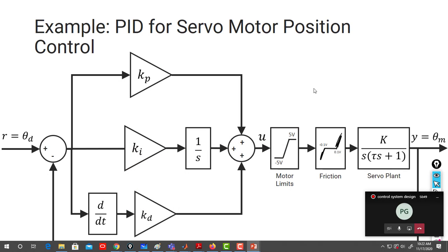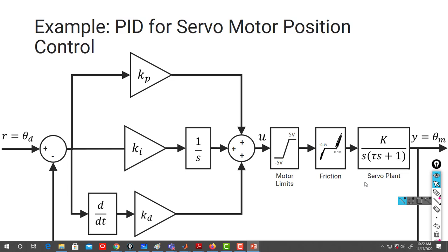Yeah, so you know, when you apply voltage to your DC motor, it doesn't directly turn on. It needs some minimum threshold voltage at which your motor will start rotating. And this is because of the, so Tariq said load, and he's right. This is because of the load of the disk itself.